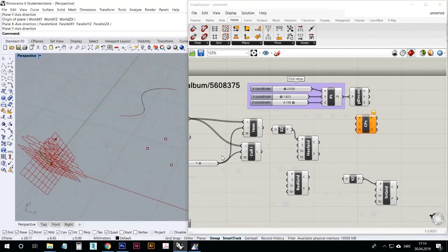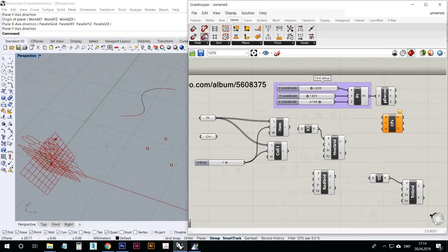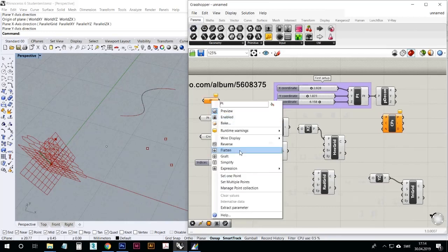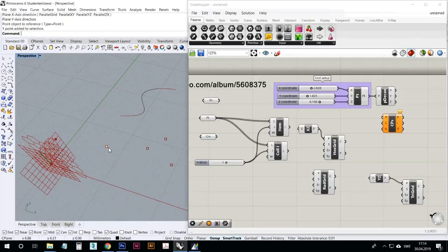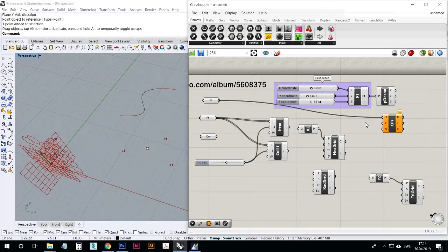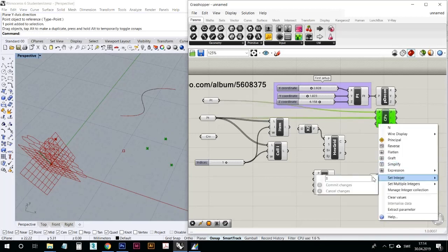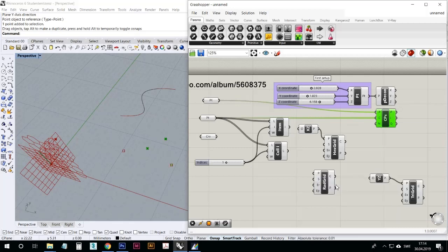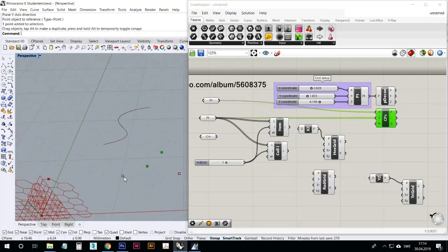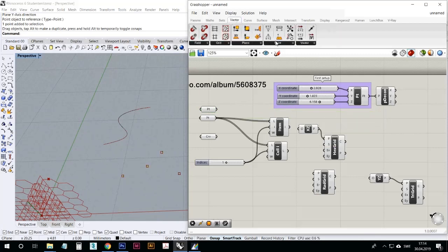For example, we can test it here. If we take one point in Rhino here, for example this one, and put it there, maybe. Point to search from, this is the cloud of points to search. And I want to find only 2. These are the closest points to that one. So that might have gone quite fast, but I'm sure you can repeat that yourselves. So very, very handy things to use.